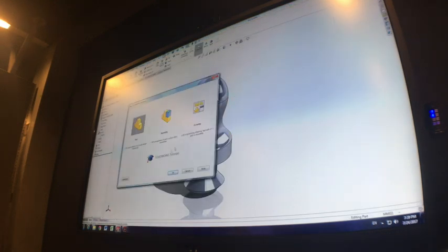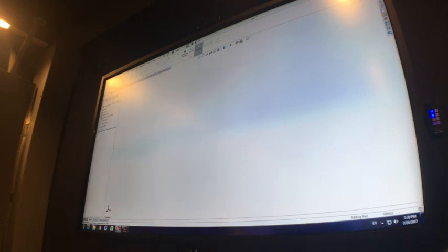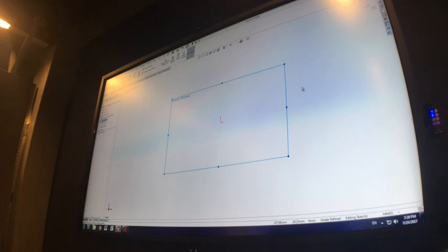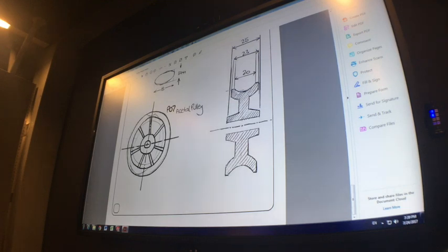So let's start this one off. Front plane sketch, and we're going to combine a couple of the skills we've already learnt with mirroring sketches as well. When you see the section view top and bottom, we only have to sketch one of those. So we're only sketching this top half, but we're actually going to halve that again and only sketch one section and then mirror that to the left.